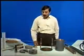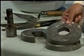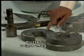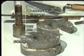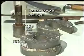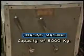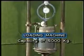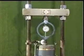Surcharge weights of mass 2.5 kg each and having a central hole of 53 mm diameter, a slotted weight, a penetration plunger of diameter 50 mm and height 100 mm, a loading machine of capacity 5000 kg and capable of travelling vertically at a rate of 1.25 millimeters per minute.